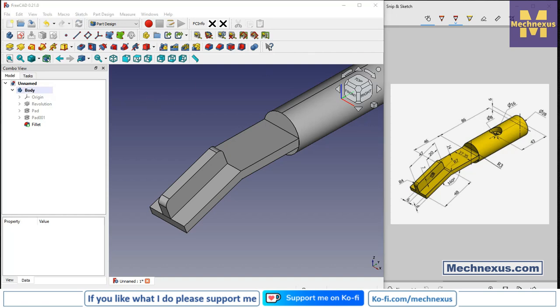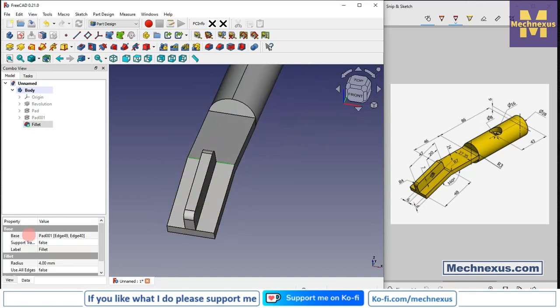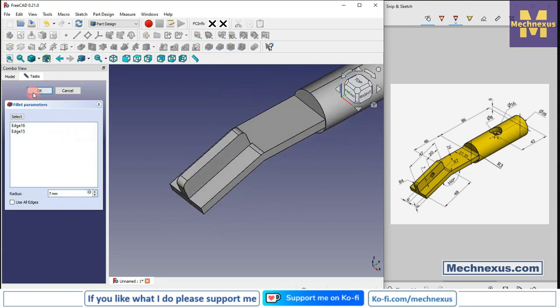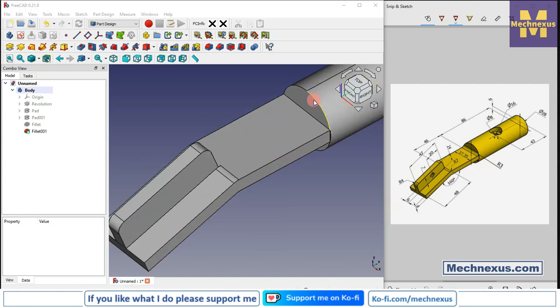Now here is a radius of 7 mm. So we will select this edge and this edge by pressing the Control key and click on the fillet and provide the value of 7 mm. Click on OK. Now we will provide the fillet of R3 at the top and the bottom.